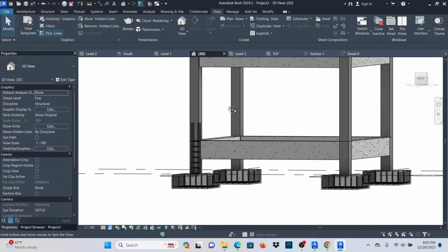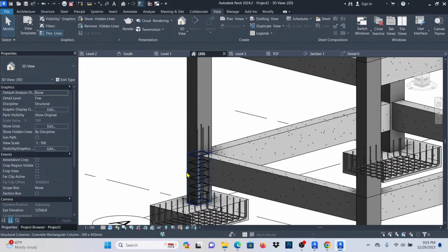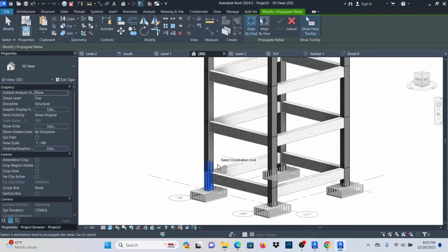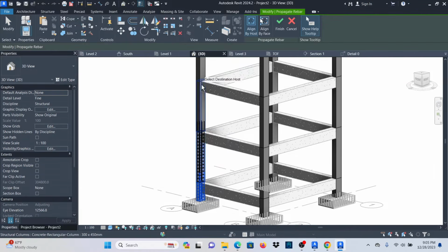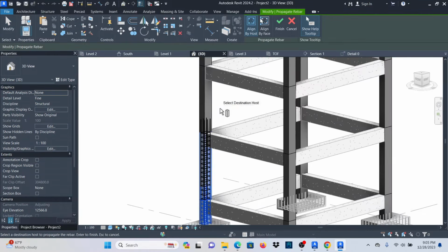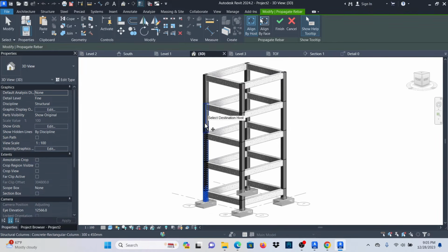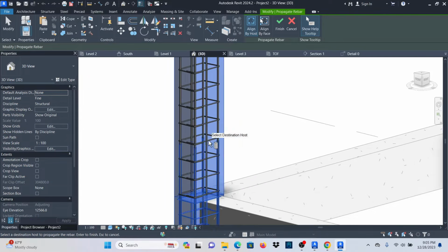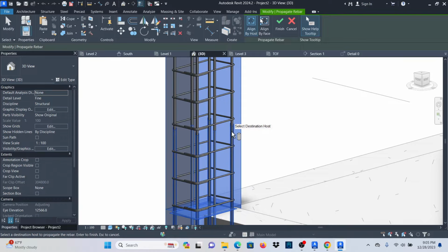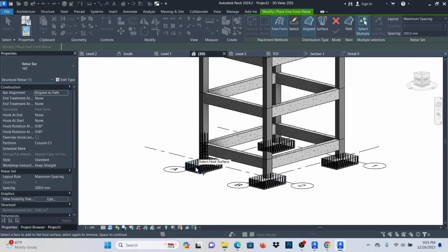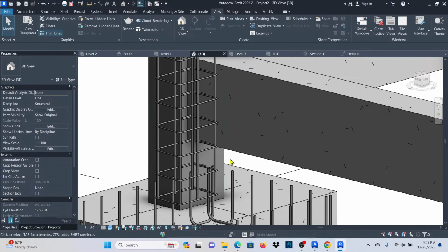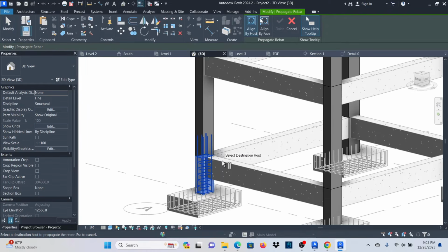Click like that. And then what I'm going to do is to just propagate the rebar all the way up to the top. I'll select on the column there, then propagate. Let me see if it's going to fit within there. Click perfect. You can see it fits there with those starter bars. I can just click there, and maybe even before I do that, okay, I'm not going to do the cranking. I'll just move this bar a bit inside. So let me cancel first of all. I'll do it once. I'll select on first. Let me cancel so that you don't get confused. You just need to click on that column, propagate, and I'll select this one and click on finish.